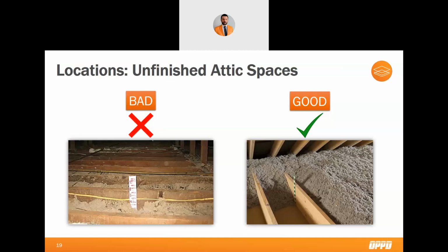This is a situation that will need to have insulation added to it, if not removed and all new insulation added. On the right, however, we see a representation of how deep the cavity is and how much is required above the top of the joist. That's where we want to see it in the attic. In this photo, we are seeing about an R38, but here in eastern Nebraska and western Iowa, a few more inches on top of that to R49 is best.